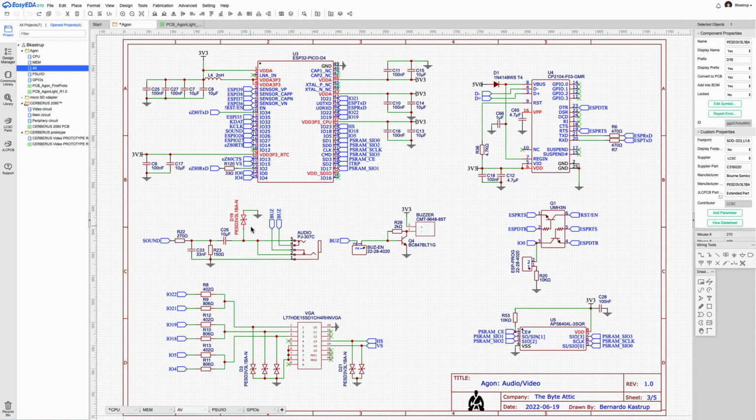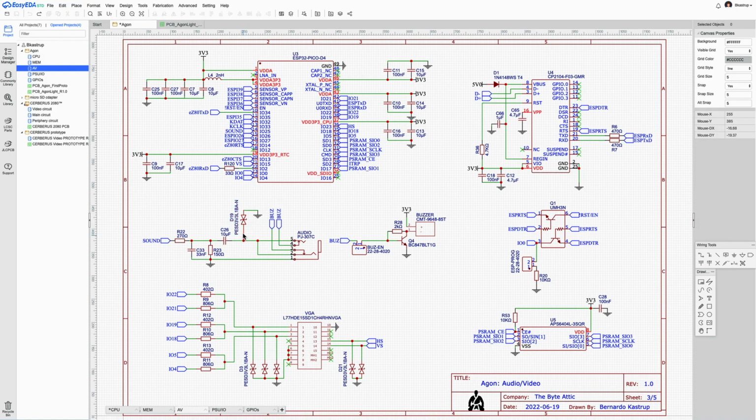This is a safety diode. It just makes sure, because this line here is connected to an output port. So if people stick their finger in there or connect a plug in there that is statically charged, through this double-sided diode, it's actually two diodes, that excess voltage is drained to ground before it goes into the rest of the circuit and gets into the ESP32 through this pin. So this is just an overvoltage protection diode, or voltage transient suppression, and whatever you want to call it.